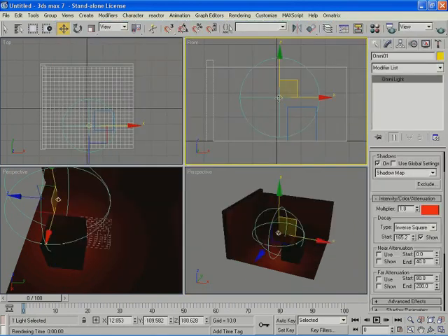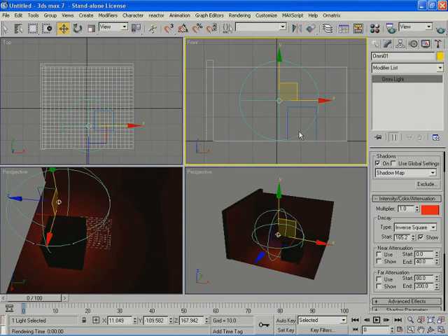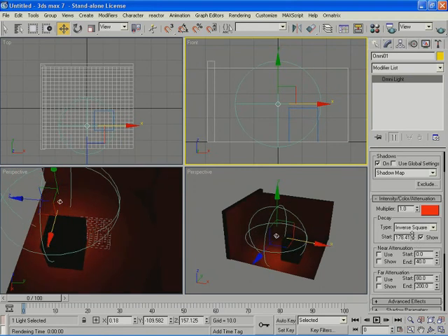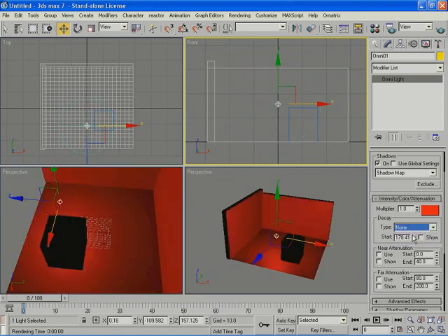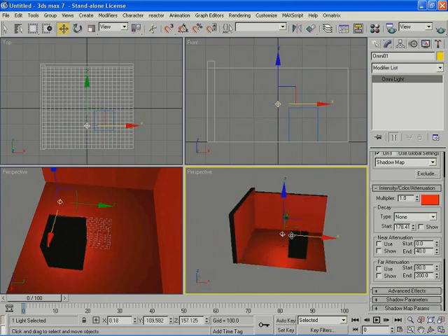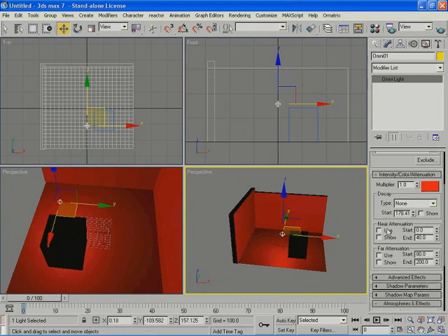So basically, you would need to use inverse square a lot, because lights don't really extend to infinity. They go to a certain extent, which is defined by this value down here. Another way to control the light is not through math with this equation, but through four values, which are called attenuation. We have two things for attenuation: the near attenuation and the far attenuation.